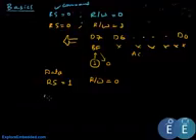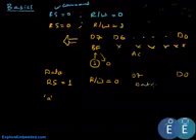So when we send ASCII for, say, letter A on the data bus D7 to D0, the LCD takes it and displays it on the LCD. So the register select, when it is 1 and read write is 0, the D7 to D0 bits will have data to be displayed. Now let us take a simple example.